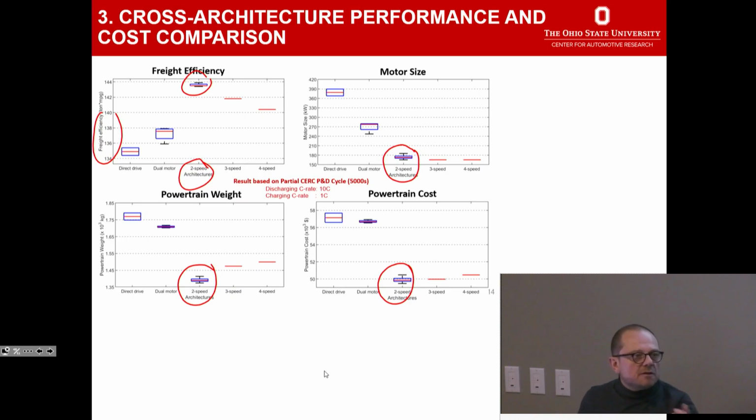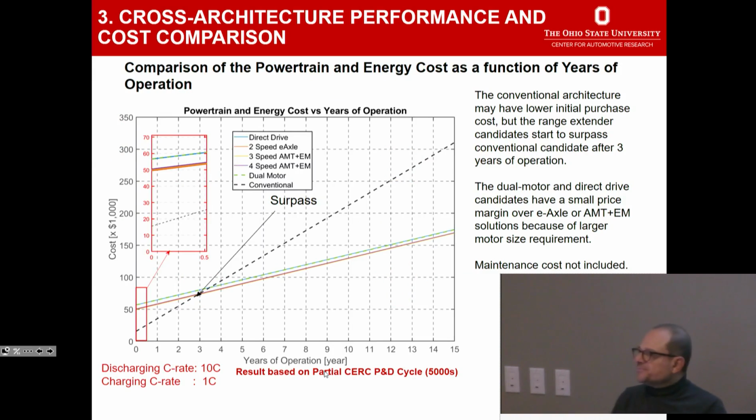So the answer that we came up with, after having compared all of these criteria, of the surviving designs that met all the specifications, a 2-speed transmission with an appropriately sized single electric drive is in fact the best answer. And I will close my comments here by saying, so now I have a $15,000 powertrain today, produced every day in Gaffney, South Carolina by Freightliner Custom Chassis with beautiful engines coming from Cummins, okay? That's a $15,000 cost for the powertrain, engine and transmission.